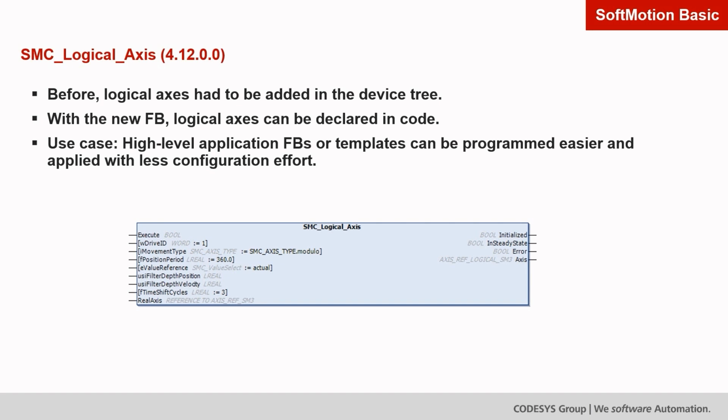Up to now, the logical axis had to be configured as a device in the device tree. With this new function block, there is now the possibility to create the logical axis dynamically in the code and to couple it to a real axis with this input here.